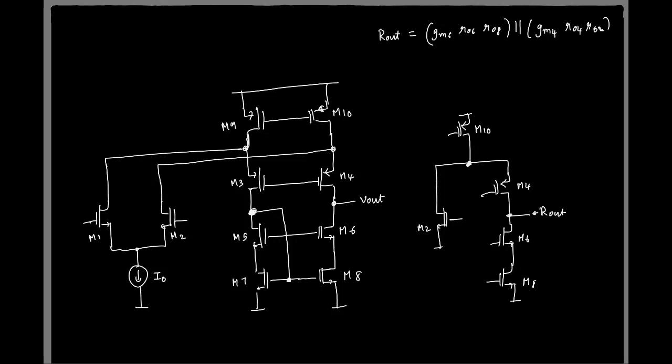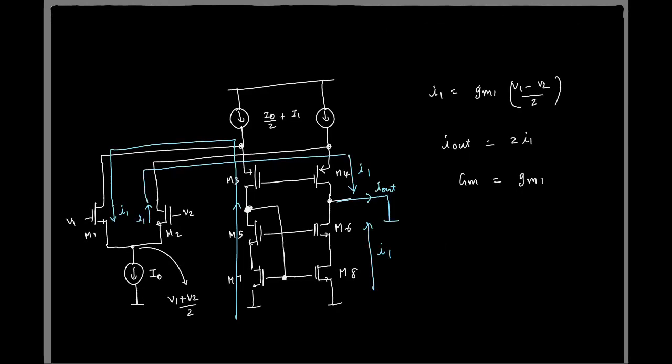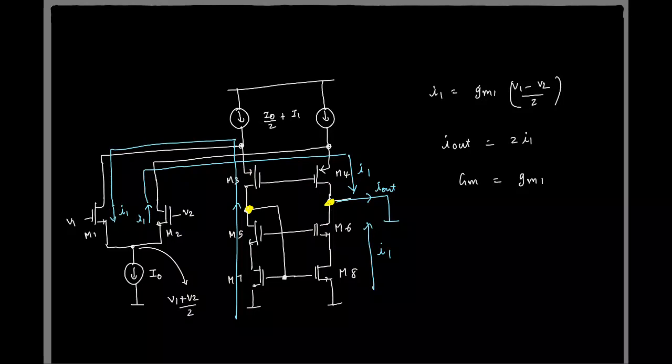So why do we assume like that? Why are they on low impedance? You told now, we shorted this part and this part at low impedance, so we assume that this is symmetric. Correct. I mean, in this case, when you're shorting the output, these two are approximately at low impedance, then we can say they are symmetric. Yeah.